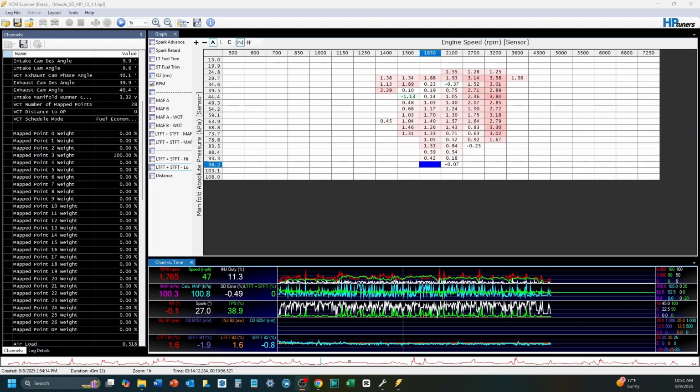Another thing in the same run I will tend to do is pick up the interstate, right? And so you're cruising at 65, fifth and sixth gear, between 2,000 and 2,500 RPM when you start, and you can get that low pressure, low load data, right, where you're barely touching the throttle, and that helps you map like 1400, 1500, etc. Where we really want to target those like 1600 and above. And you also want to get high pressure situations at those low RPMs. And the interstate's perfect for that because you can be in sixth gear and absolutely floor it in this state, right?